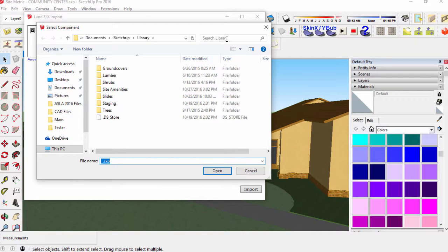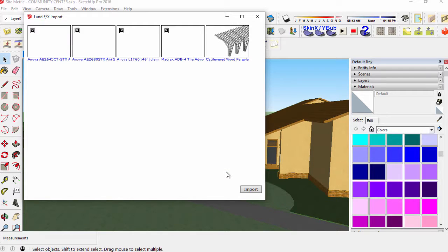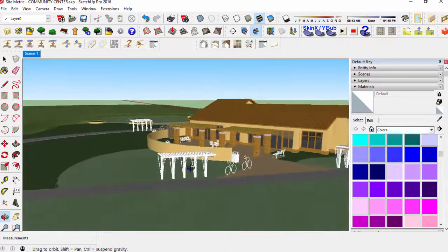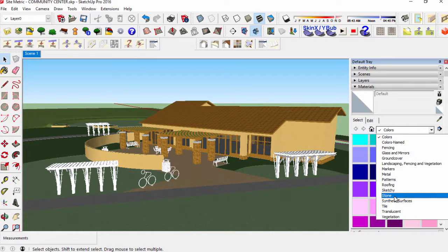Click on the blank tile to assign your saved SketchUp component. If you're on Cloud Data, that's all you need to do. You can now start using this Amenity Refnote in your design, and all instances will use this SketchUp component.